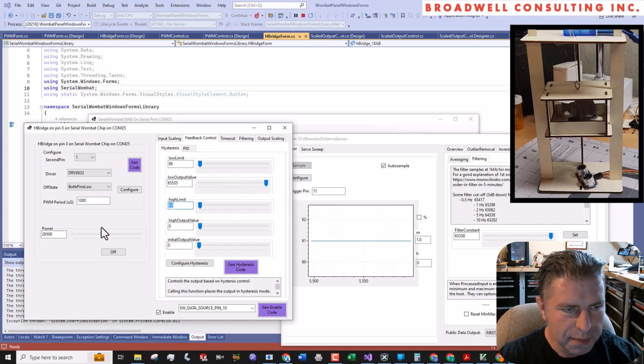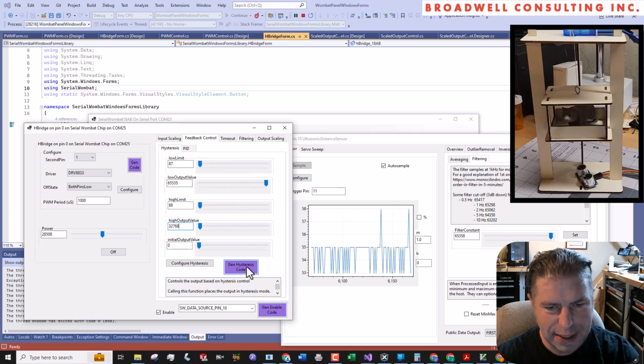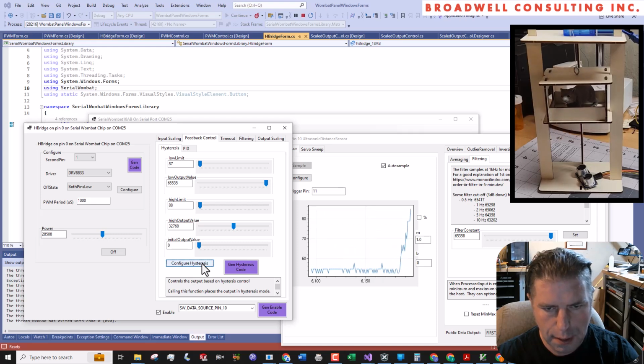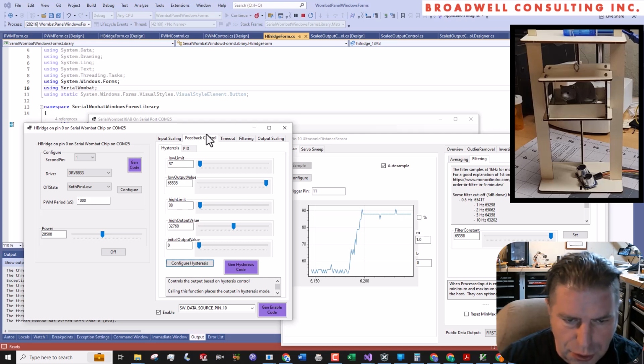At 87 or higher, the mid value, which shuts off the motor. So let's send it up to 90. We'll stop it at 87 and see if it overshoots. And we were shooting for 90, and we got very, very close. So this hysteresis is definitely how we want to try to control this.